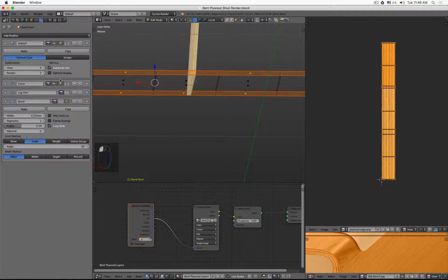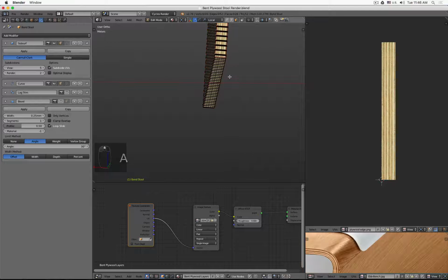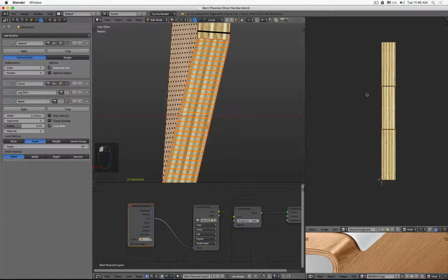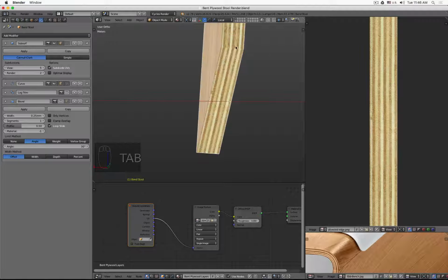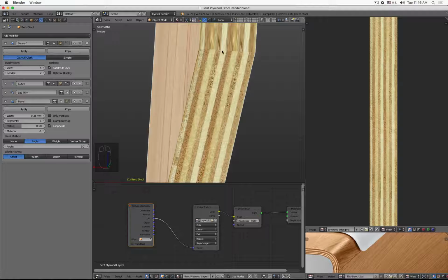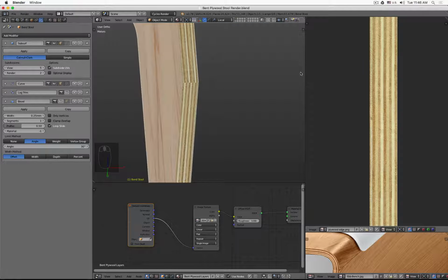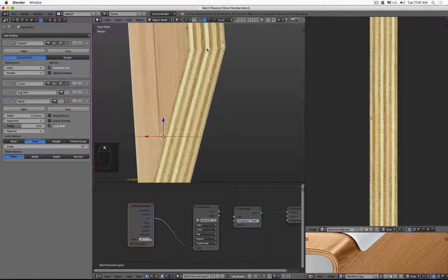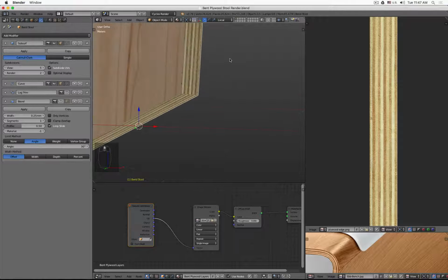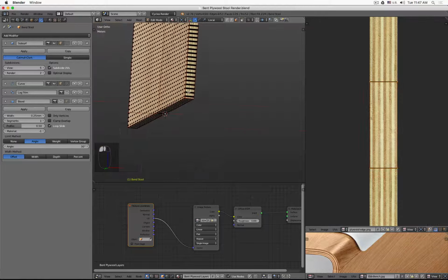So hold on. We can go to edit mode, turn the sub-D on if we want, and we can turn the curve thing on so we see all the different faces. So there's number one. Okay, and I will try this one out. I will rotate this face 180 degrees. See there, now it matches better. Okay, what about there? It doesn't match there. Okay, what's up with this position? That matches. Okay, good.